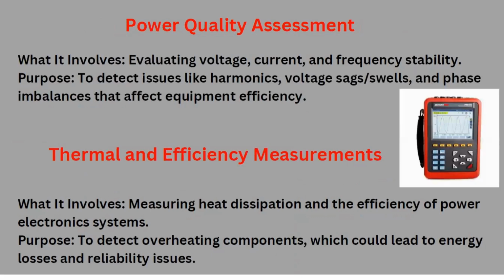The third one is power quality assessment, and the fourth one is thermal and efficiency measurement. Now, what is power quality assessment? Evaluating voltage, current, and frequency stability, whether continuously the current, voltage, and the frequency of that particular current is stable or not. The purpose is to detect issues like harmonics, voltage sags, swells, and phase imbalances, and their effect on equipment efficiency.